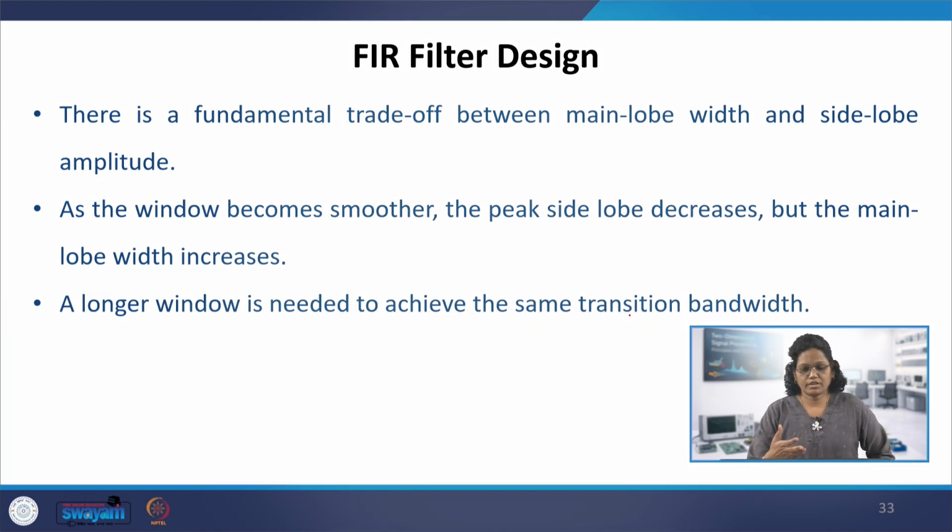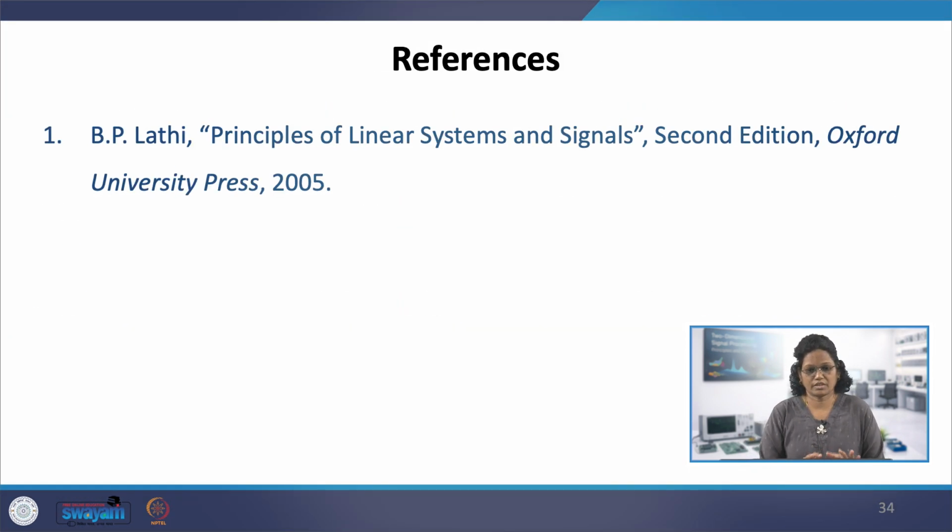So to conclude with the filter design, for the 1D FIR filter especially, the common method is the window method, in which you choose the desired frequency response and get the inverse DTFT, so that we have the filter coefficients hd(n) spreading over minus infinity to plus infinity, and choose the window function. Multiply these two to get the practical filter, that is, the truncated coefficients. If we take the window function's frequency response, for the rectangular window we will have the sinc function. Convolving these two in the frequency domain, that is Hd and W, we get the actual filter response,